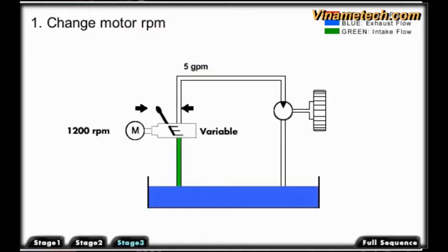For example, the displacement of an axial piston pump is determined by the distance the pistons are pulled in and pushed out of the cylinder barrel. Since the swash plate angle controls this distance in an axial piston pump, we need only to change the angle of the swash plate to alter the piston stroke and pump volume.